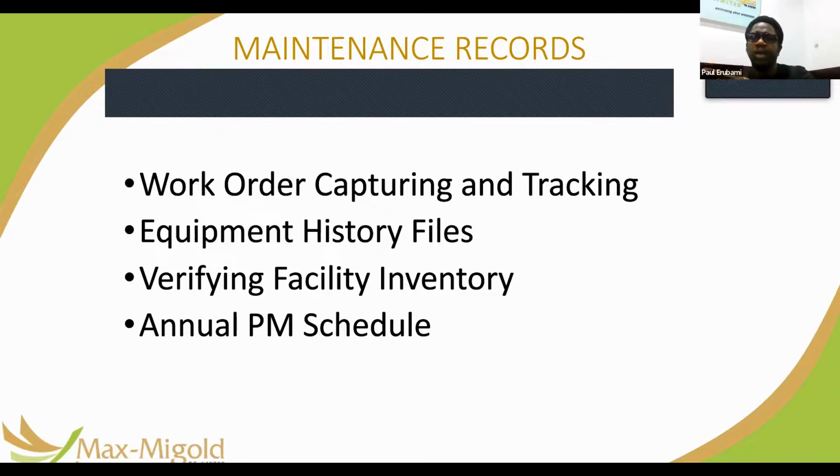And that work order becomes the way of logging. That is, from that work order you now log into a spreadsheet for reporting, a logbook, or a CMMS. Of course, if you're in a CMMS, computerized maintenance management system, that work order will be electronic. So you fill in the information and then it automatically goes in. Everybody that works on that work order will feed the information back into the system.